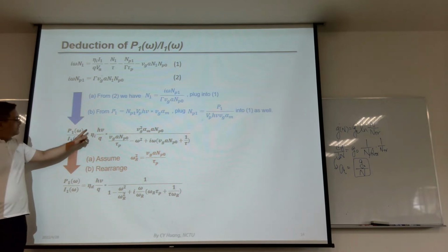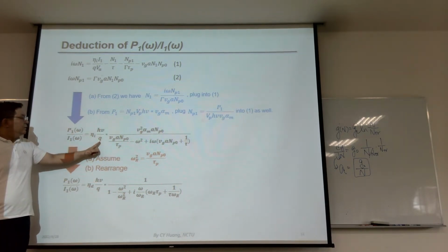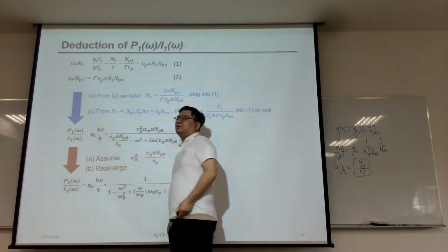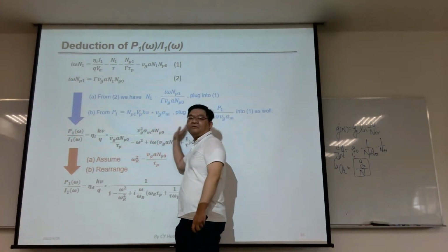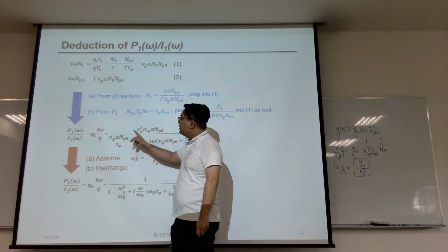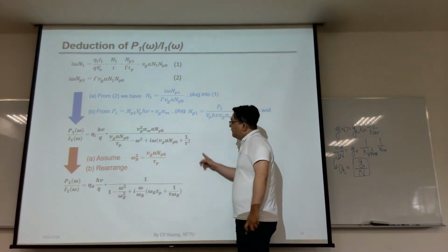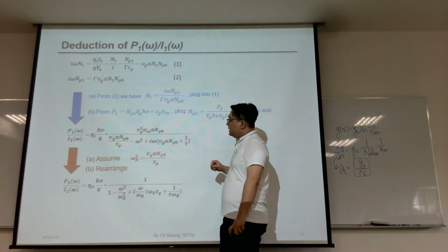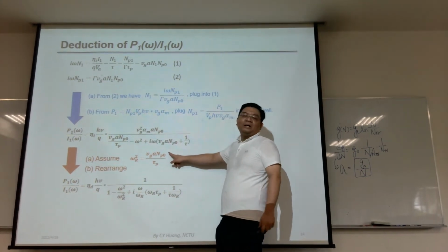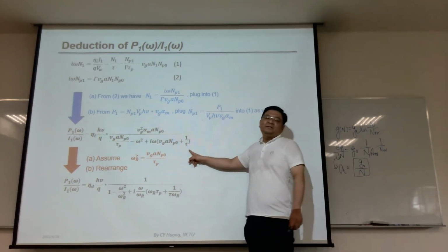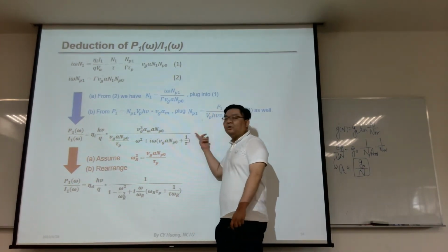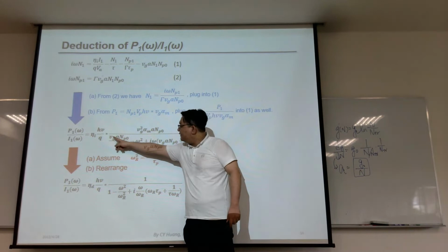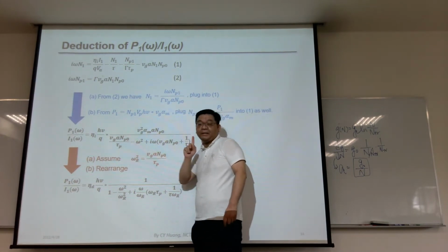It will be zeta I divided by h nu q. This is if the omega is 0, everything stops here. Then you don't have the following term. But now omega is not 0, so you have a very huge term followed. And some geniuses know how to further simplify the whole equation by defining a parameter, gamma Vg a NP0 divided by tau p.